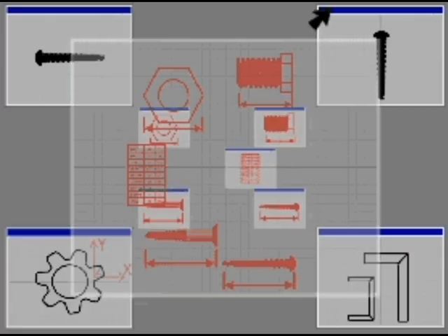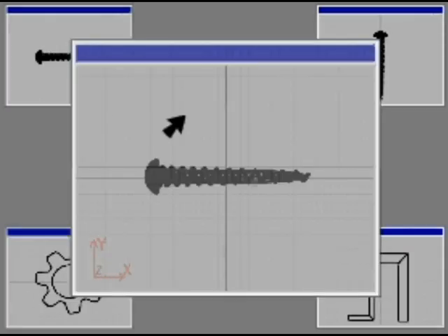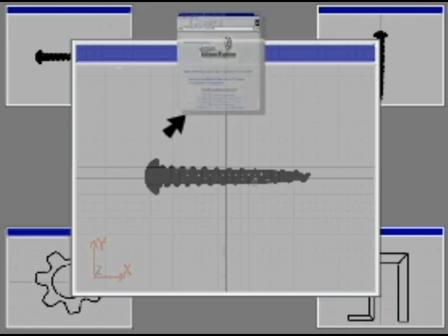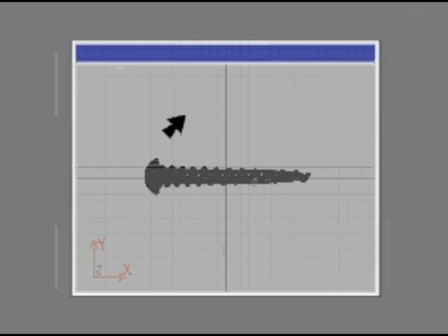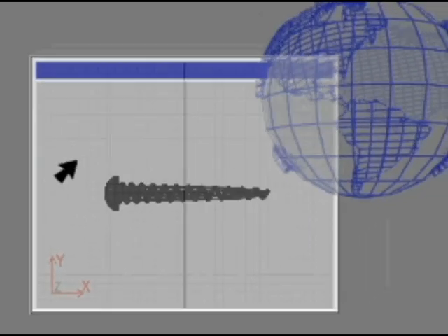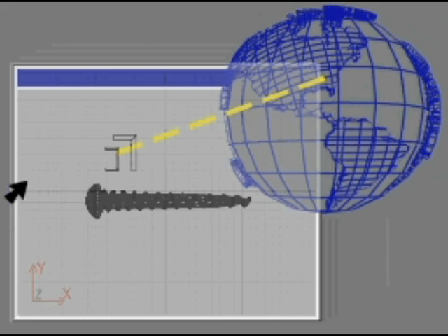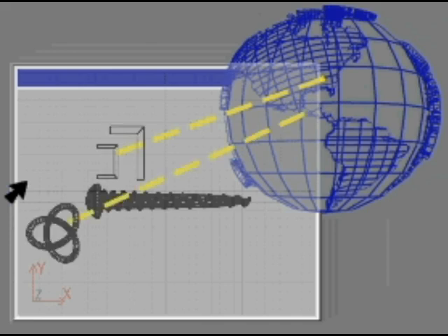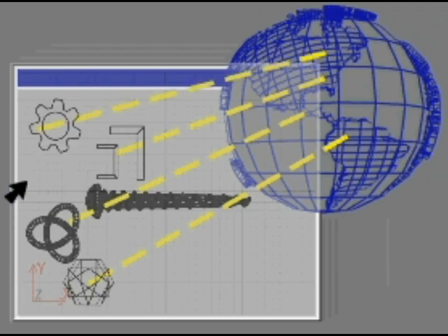You can drag an entire drawing file into the current drawing. You can load drawings from websites and FTP sites into the Design Center palette using the integrated web browser, and then drag components from these files into your current drawing. Design Center serves as a central source for design data and facilitates collaboration between design professionals. Using Design Center to access drawing content from several sources dramatically reduces the time you spend creating drawings and ensures consistency across all drawings.